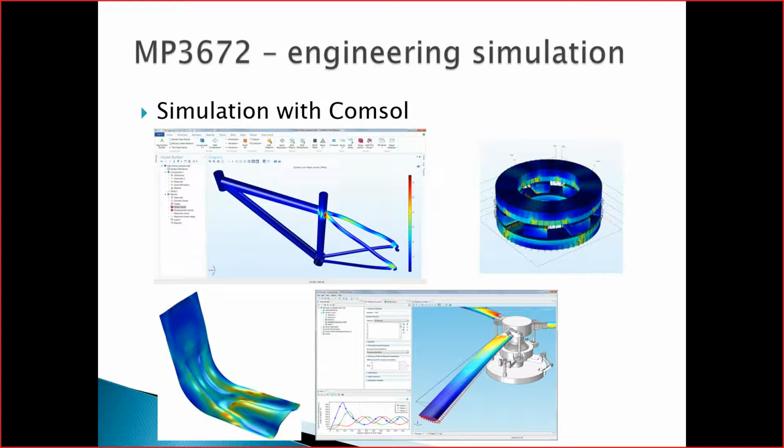If you look at the bottom right, where you've got the rotor blades, this is really sweet. If you are into wind turbines, or any type of rotor system, this is really good, because it allows you to apply your variance to it. You can have a wind force against the front of it, and as it hits, you can get the vibration straight from it as the blades are spinning, and you can look at possible points of fatigue depending on the material you're using. My PhD was in this, so I do rabbit on way too much about it. Once you've got it, you can then pass this through to Sim Multibody and actually run it on the electronic side as well, so you can look at how energy efficient this is based on the results you're getting. And this is all software that we have on the system already.